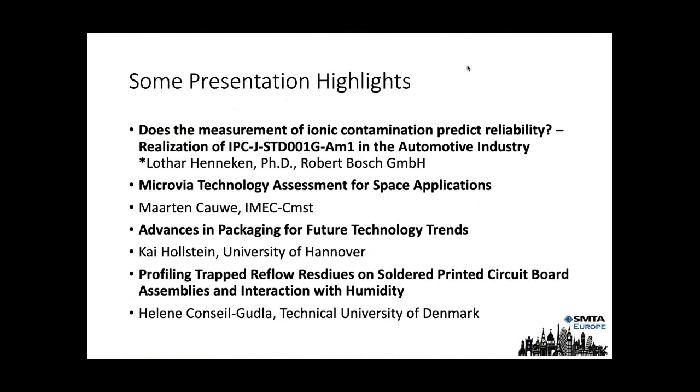to everybody who listens. This last one is something which is becoming more and more prevalent in harsh environment and also in high reliability automotive areas. Reflow residues which get trapped under the bottom terminated components or the QFN type things, residue is hard to cure in these areas, so a lot of the residues are a little bit active and not benign, which can cause some problems.